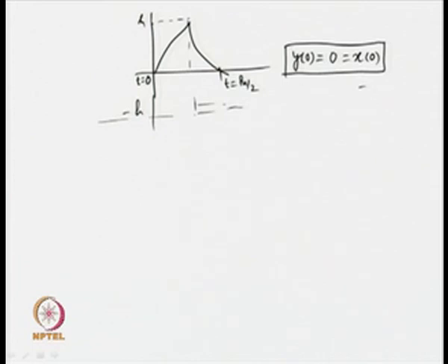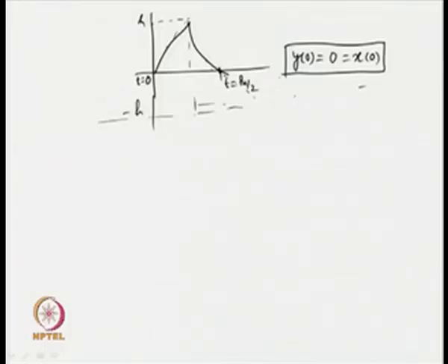Further, for the limit cycle condition, we know that the positive half and the negative half have got symmetricity, they are symmetrical. That means, we have got half wave symmetricity and therefore, y(pi by 2) will be equal to minus y(0).